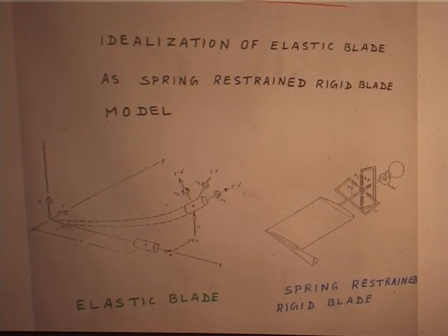Okay. You try to match the fundamental natural frequency of the blade, only the fundamental first mode, because an elastic blade will have infinite natural frequencies: first mode, second mode, third mode, fourth mode, etc. If you study vibration then you will know. Otherwise, you know a spring mass system: one spring mass, single degree of freedom, one natural frequency. If you have 2 degrees of freedom, you have 2 natural frequencies, 3 degrees of freedom, 3, infinite degrees of freedom, infinite natural frequencies. Okay.